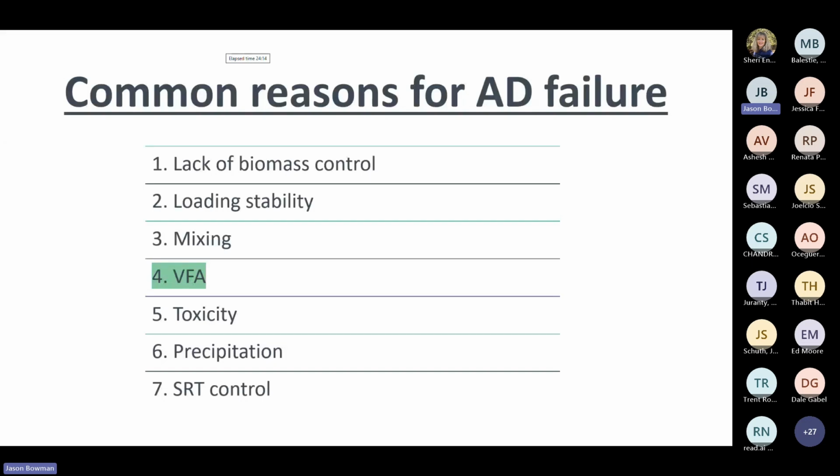So traditional digester systems generally adapt for this by trying to understand what waste is being added, what your feedstock is, and continuously monitoring the pH and the alkalinity as it relates to the incoming organic load. But still, at the end of the day, for these classical systems, there's really few external control mechanisms to help balance these systems, beyond these initial operational inputs: your feedstock, your pH, and your alkalinity.